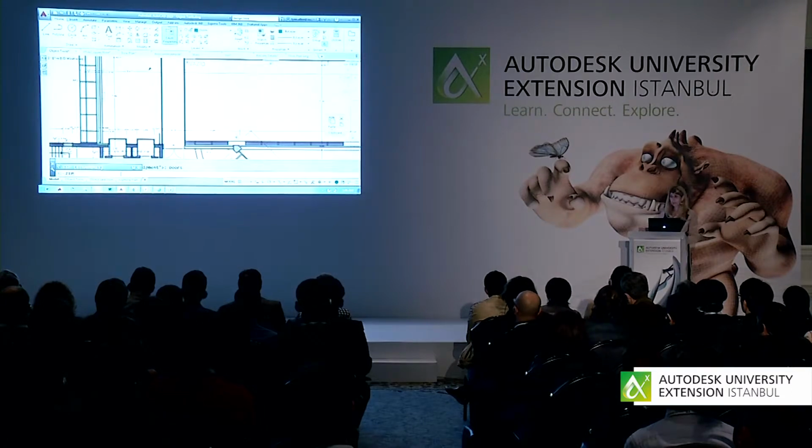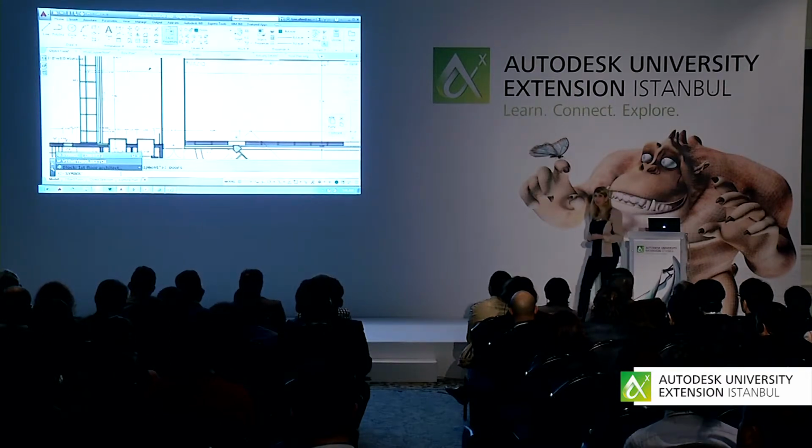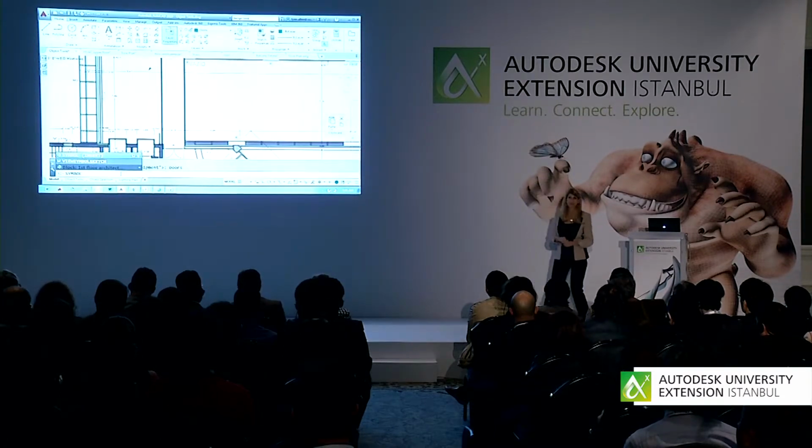For example, if I type in zip, you'll see that it does e-transmit. If I were to type in symbol, that's a common phrase inside of MicroStation, which is a totally different product, right? You will see that the insert command also shows up as an option. You will find that you can add your own set of commands to AutoCAD that maybe you like to use that AutoCAD doesn't recognize very easily.